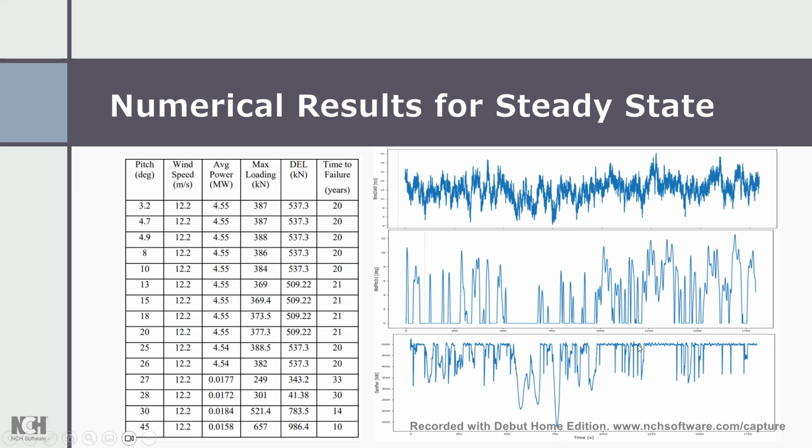But right here, when we get max, about 5 megawatts, our blade pitch goes from 7 all the way up to almost 12. And you can see how the wind is. So you can just see how things automatically kind of change themselves, since they simulate the sensors in OpenFAST.